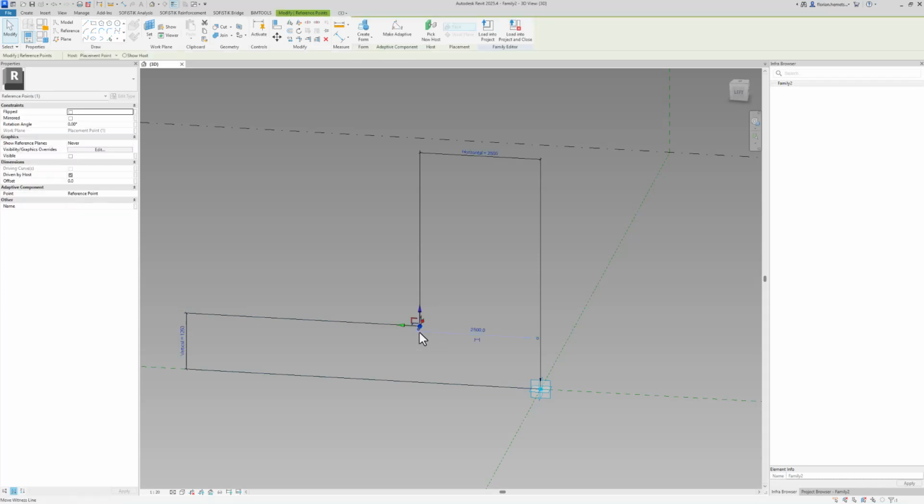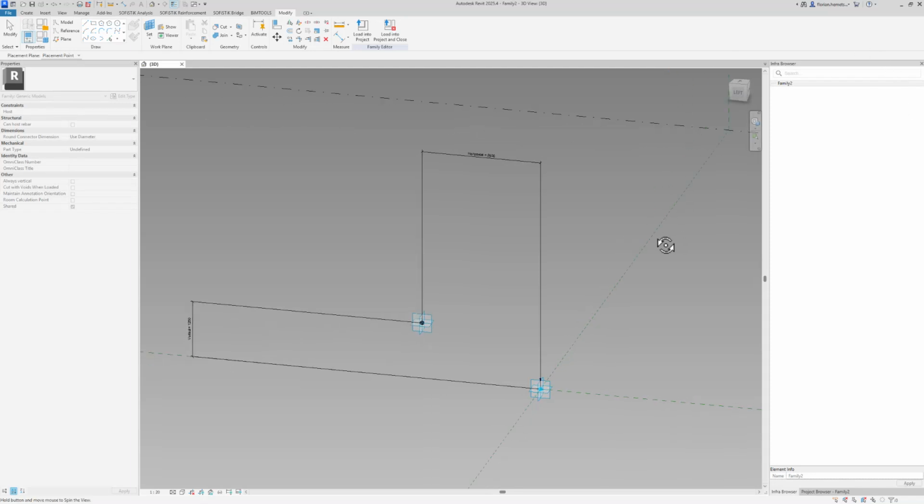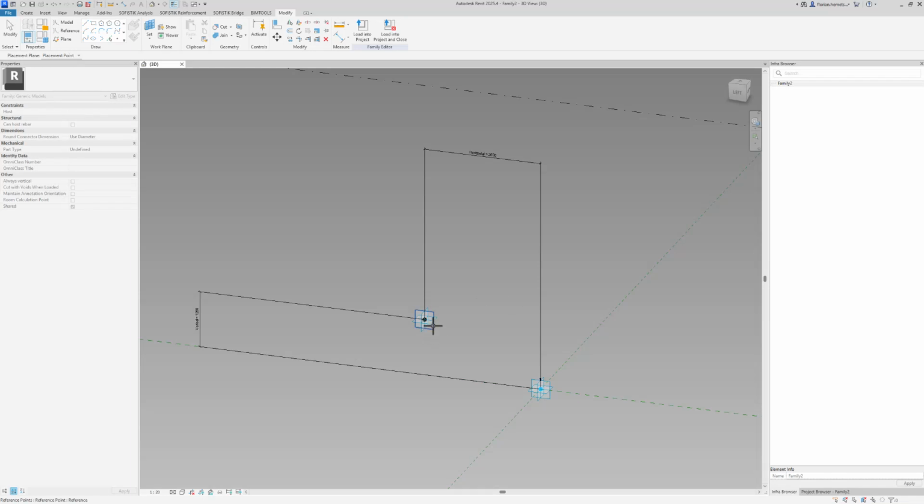So this point shall be my new reference, and to easier display it, I want to show the reference plane of my new reference point. Next up, I want to talk about the planes. You can see that this reference point has a plane in the orientation of our input, this plane here, a longitudinal plane and another longitudinal plane aligned to horizontally. The way that offsets of reference points work is that they work orthogonally to the selected plane.